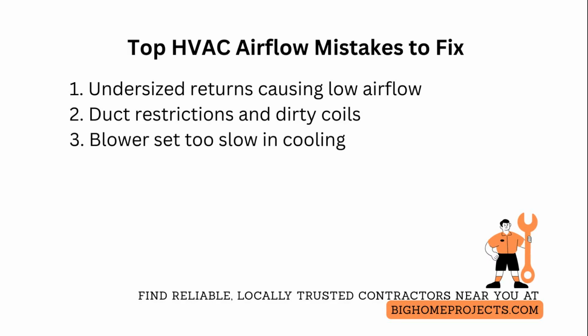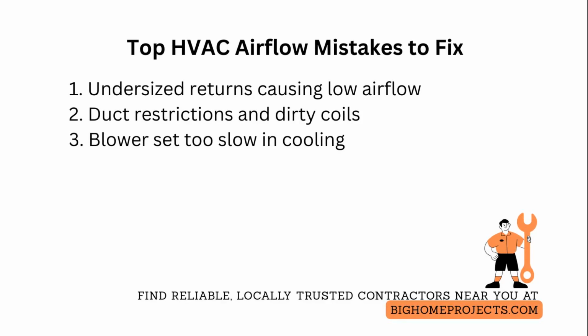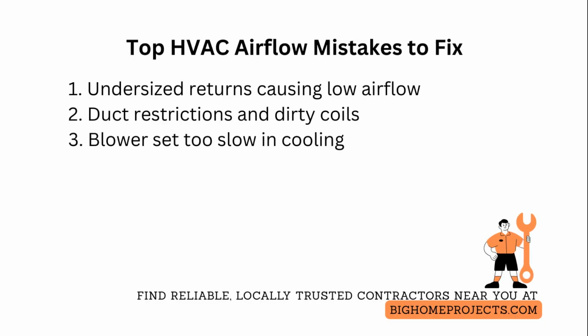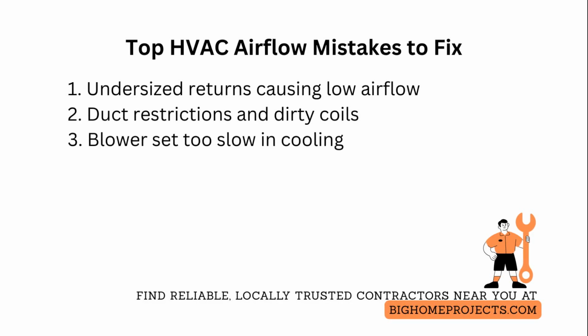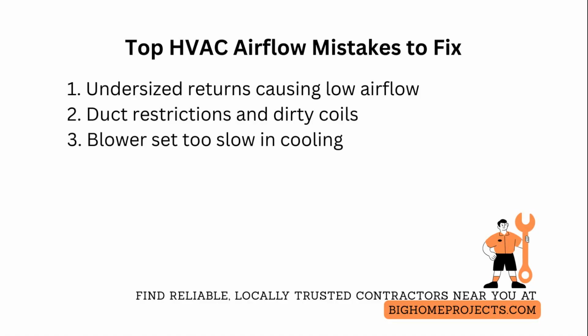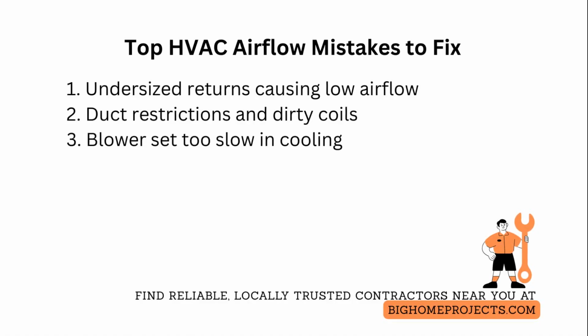Another frequent issue is duct restrictions from crushed flex or dirty evaporator coils that limit cooling capacity and raise humidity. Verify by comparing static pressure before and after the coil, and by inspecting flex, bends tighter than 1 duct diameter radius. Then straighten flex, add metal elbows, clean the coil with manufacturer-approved chemistry, and remeasure.